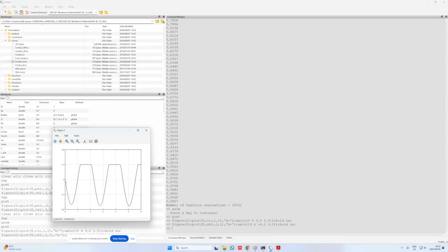So we can see initially the velocity of the block is negative, so that means that the spring is pulling the block back towards it, and it then achieves this parabolic relationship that I have over here until it reaches a zero velocity again, at which point the spring is now completely compressed, and now the spring is starting to push the block away again until I reach the maximum speed, which is then equal to the conveyor speed in this case.